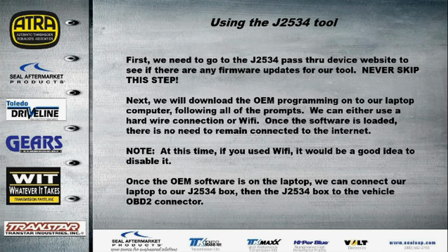But in most applications, we don't want to do it, because we can actually initialize the vehicle computers. In the case of Chrysler's, they can ask you, do you want to erase the module? And of course you'd be tempted to say yes, because I'm programming, and you would think it's natural. But you don't want to do that, because you can end up in a whole world of hurt, and you can blank out all the modules in your system. So again, at this point, unless instructed to do so, you don't want to hook up to the vehicle's OBD2 connector through the pass-through device with your laptop.